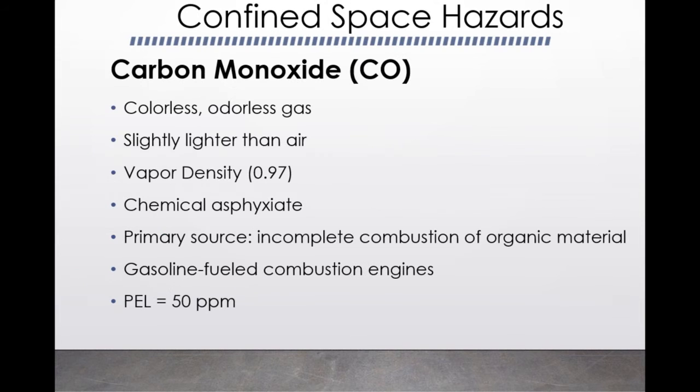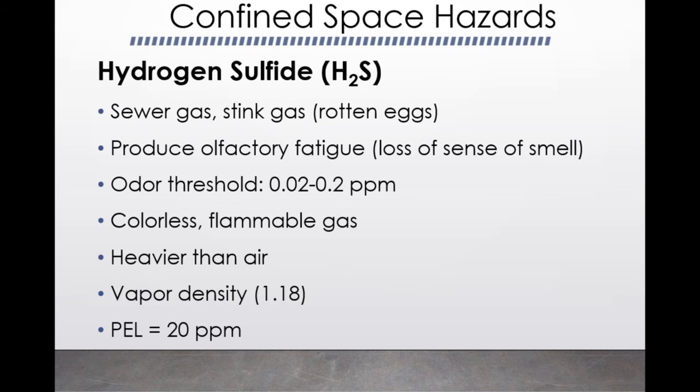And then toxic carbon monoxide, it's a colorless, odorless gas, slightly lighter than air, but it's going to be pretty much right around the same breathing zone that you're in. And the chemical is also an asphyxiant. The primary source is incomplete combustion of organic material, and you can see it in gasoline-fueled combustion engines. And then your permissible exposure limit is 50 parts per million of carbon monoxide.